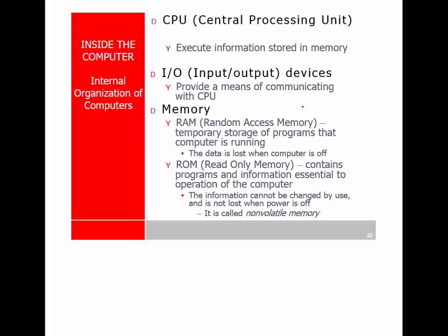But RAM and ROM are different. ROM is more common in embedded systems. When we look at the software we're going to write in this class, we're going to be using more ROM. Next semester, when you take microcontrollers, pretty much everything is in ROM. A microcontroller might have 64K of ROM and 256 bytes of RAM, and that's enough. So it's the other way around.